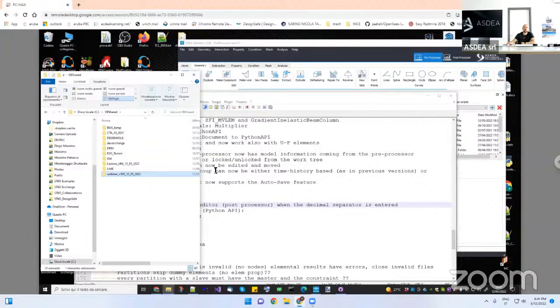So if you want, you can create a file with this one, start with a very small number, like 1e-3, and try to see how it changes, okay? I did some tests, and I can tell you that a very large number for KP is going to be a problem, because actually there is no stiffness for the water pressure. So start with a small number, plot the profile of the pressure, and see if it is continuous through the two domains, okay? It should be continuous. I think that with a very small number comparable to the permeability coefficient, it was fine.